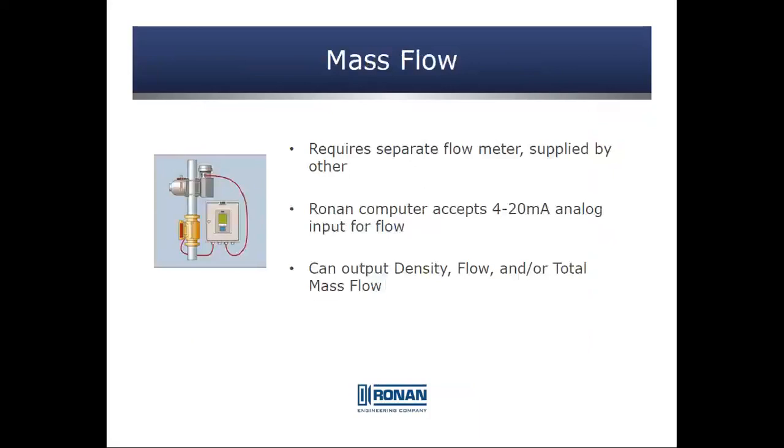I commented about mass flow a minute ago. Here's just specifically mass flow. It requires a separate flow meter, getting a 4 to 20 input, and then we can calculate the mass flow plus give an output of density and weight. Density and flow.